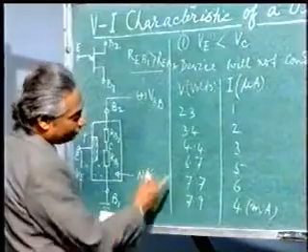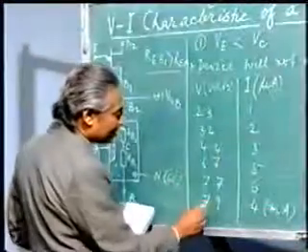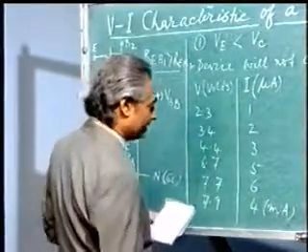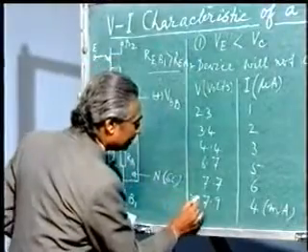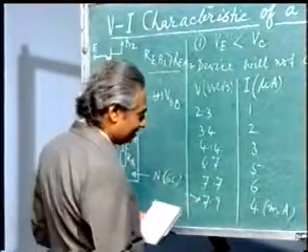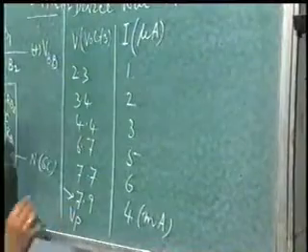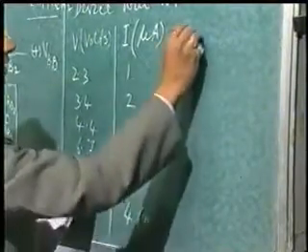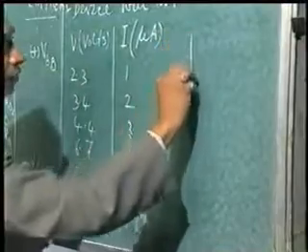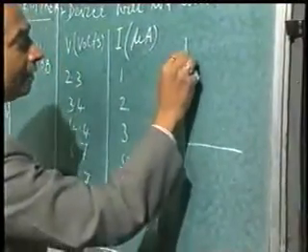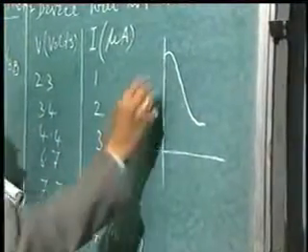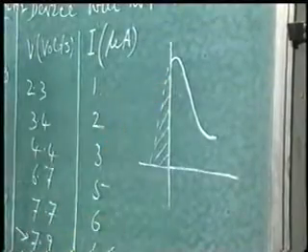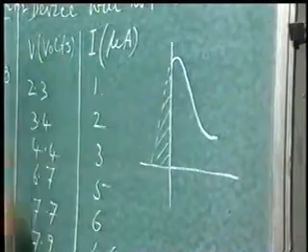Now here you will find that from 7.7 to 7.9 volts there is a sudden jump in the current from microampere to milliampere, and suddenly there is an inrush of current. So it clearly indicates that at 7.9 volts the device has triggered. That means this is the peak point voltage and this is the corresponding current. Now here we can draw the characteristic like this with these set of readings, and you will receive a characteristic like this. You will not get this part which is imaginary or the cutoff state. We can get this part of the characteristic with this set of readings.